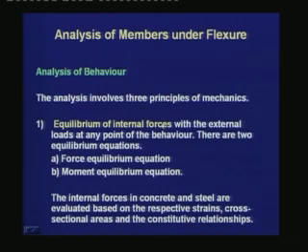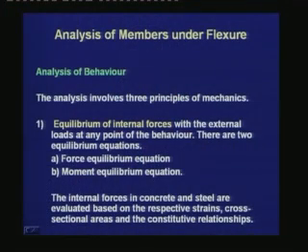The analysis involves three principles of mechanics. First, the equilibrium of internal forces with the external loads at any point of the behavior. There are two equilibrium equations, A, the force equilibrium equation, B, moment equilibrium equation. Earlier in our analysis for ultimate strength, we had come across these equilibrium equations at ultimate, but now we are saying that the equilibrium is maintained throughout the loading history. That means at any point of the loading history, the longitudinal forces are under equilibrium and the internal moment is equal to the externally applied moment. The internal forces in concrete and steel are evaluated based on the respective strains, cross-sectional areas and the constitutive relationships.